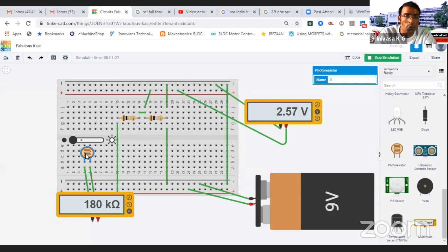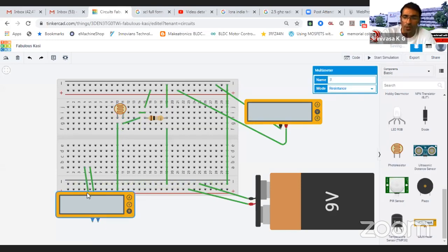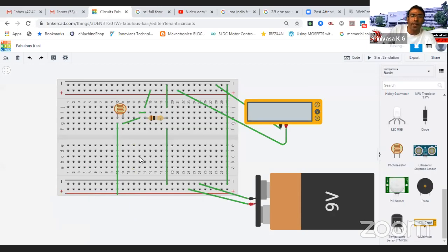So let's use this resistance in this voltage divider. I'm not going to do anything else, I'm just going to change this resistance into a variable resistance. For that, I'm going to delete this resistance and connect the LDR in replacement of R1. After doing that, let's see how the output voltage varies according to this resistance.